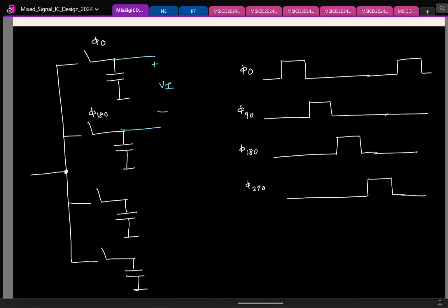I multiply with a term which has 90 degree phase shift and a 180 degree phase shift from 90, that is the differential version. This will give me the quadrature. So now all you have to do in principle is take Vi, give it to an ADC, quadrature, give it to an ADC, and in principle a skeletal receiver is done.